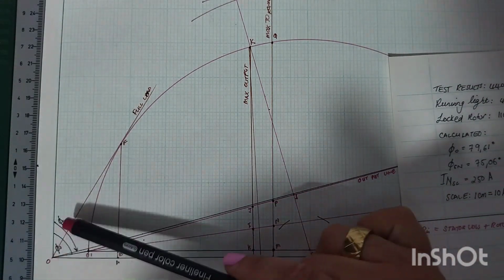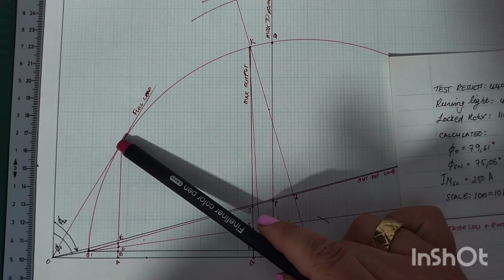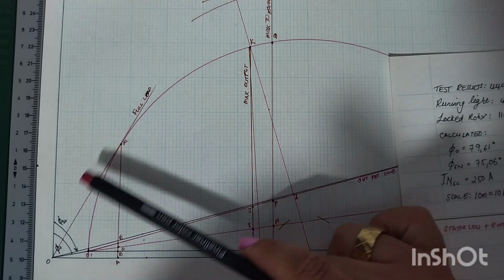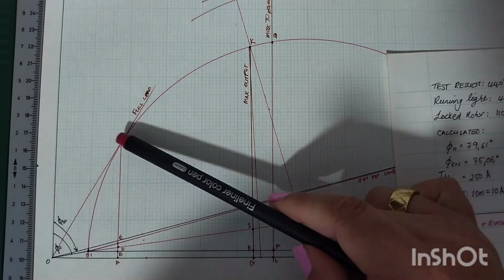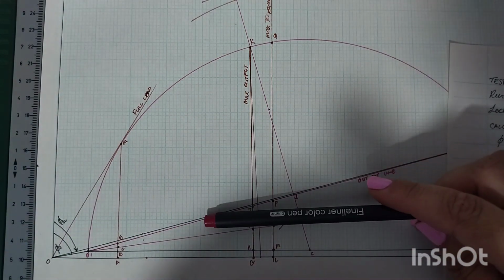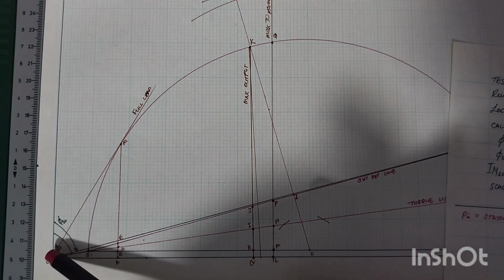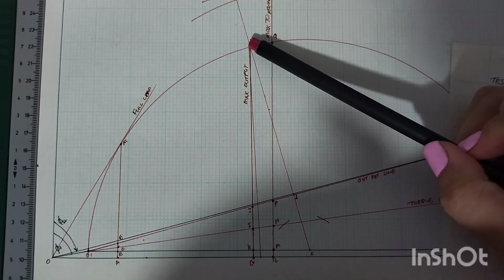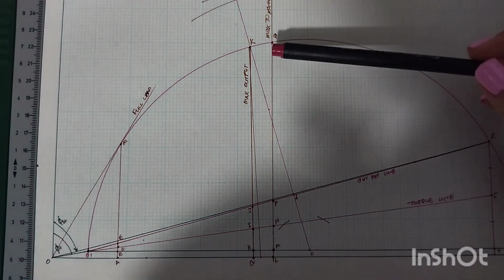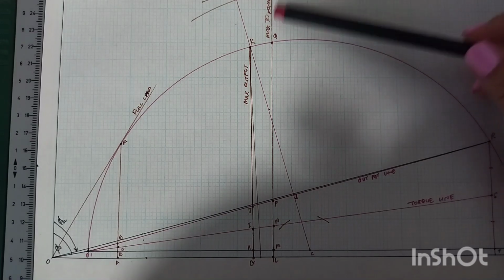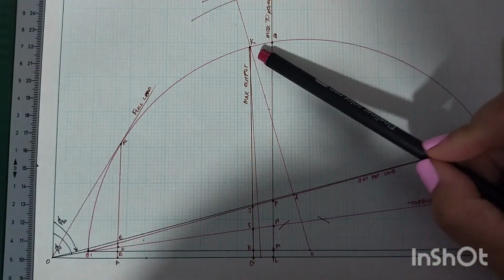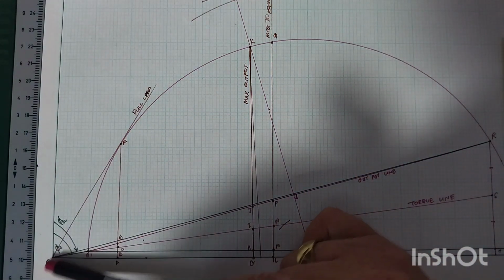So how do we take data from the circle diagram? Any line drawn from the origin of your graph to the perimeter of your circle for any load is your current at that load. So right now I'm pointing out that OF would be your input current at full load. If you needed to calculate the input current for max output, you would draw a line from your origin to the point on the perimeter of the circle on your output line. And also for max torque, you would do the same. You would draw a line from your origin to the max torque point on the perimeter of your circle, and this would be your input current for those conditions.